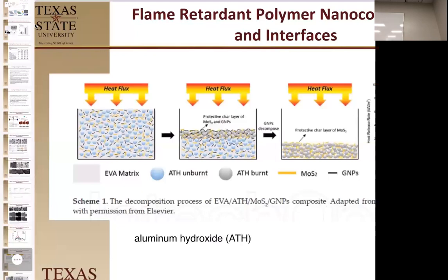Well, graphene can burn if there's oxygen, okay? Especially if it's graphene oxide with a lot of defects. So what can happen is as it's continuing to burn, all the carbon and all the matrix goes away. You're left with the dehydrated aluminum hydroxide and the molybdenum sulfide, generating a compact and structurally sound layer. The nanoparticles of the dehydrated aluminum hydroxide would not create a structural layer, but the platiness of the molybdenum sulfide plates kind of binds them together to give us this nice char.